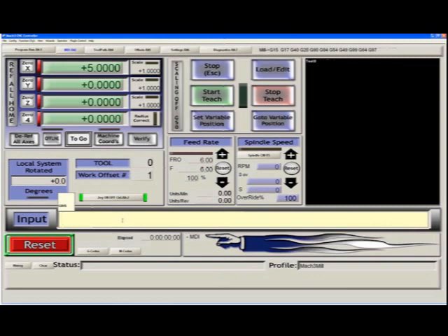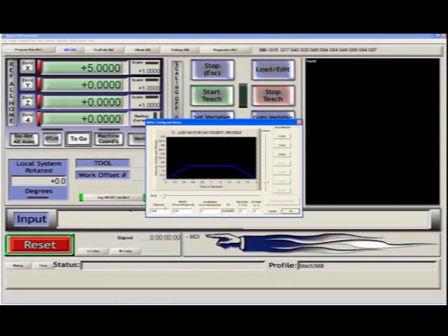This is all set up by the motor tuning steps per inch. If we go up here and bring up motor tuning, you can see that for each axis there is a steps per. This needs to be set to the number of steps the system needs to send out to move your axes that amount, 1 millimeter or 1 inch, depending on the selection you have selected for the system. The acceleration and the velocity you should set to a comfortable level prior to doing anything, and hit Save Axes for each axis. You can then adjust your steps per inch to make the system accurate.